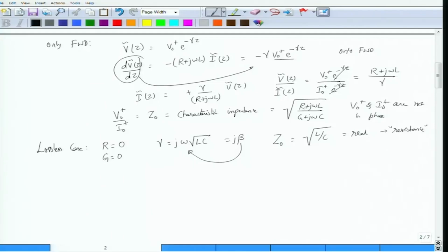So, if this is a resistance, then there will be power dissipation, and that actually brings us to a nice paradox. We said that this is a lossless case, but then we saw that the characteristic impedance turns out to be like a resistor. So, if for example this is your V0 plus and there is a current I0 plus, the equivalent transmission line would actually look like a resistor square root L by C. But we know that a resistor is a passive device which basically dissipates energy.